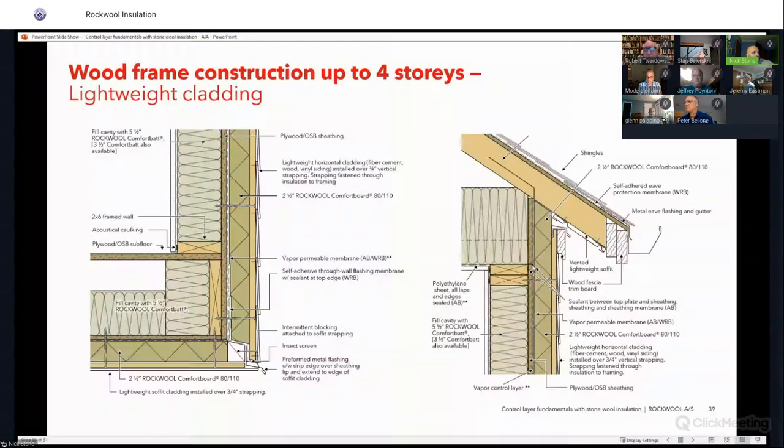As we have an insulation plane that's a flat ceiling, again, as our WRB, I talked a little bit about this earlier, as our WRB comes up, we really want to be able to have it connect to the inside, to the air control layer in here. Oftentimes this doesn't happen, so it's good to talk to your framers before you put your roof trusses on.